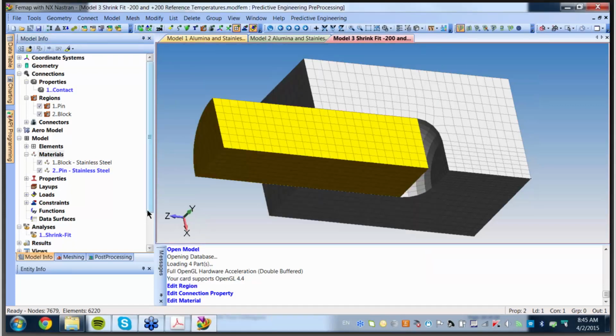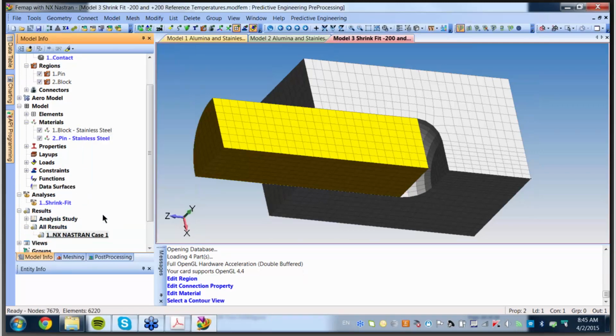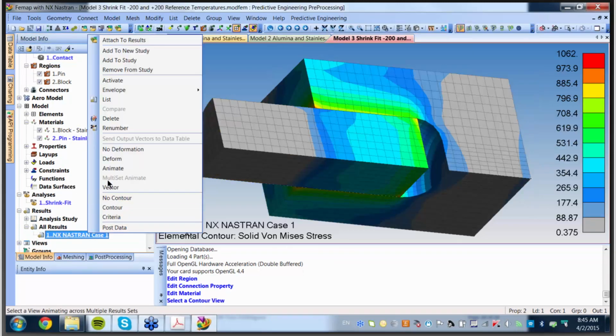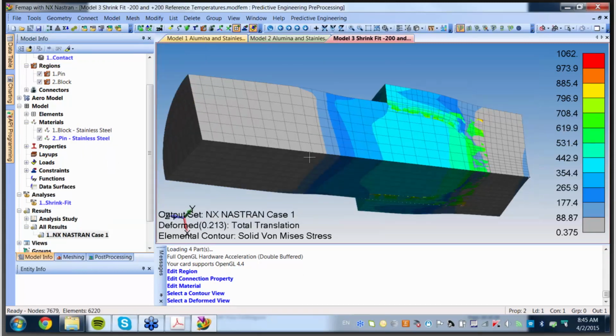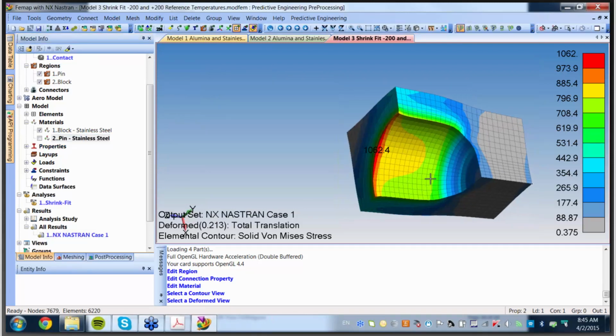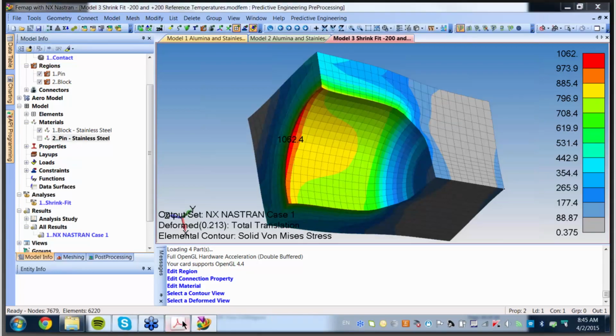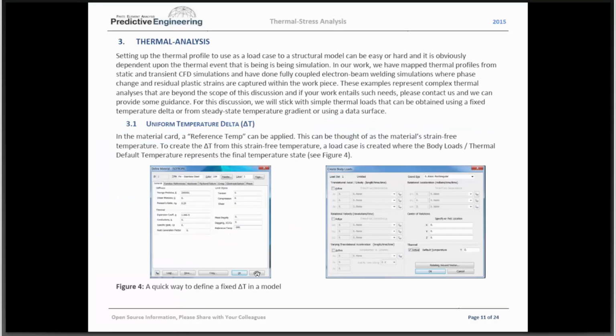And the results are down here. You can look at the deformed shape, and of course, that looks crazy, doesn't it? Because of the pin, so we'll just go in and blank it out. Then you get this beautiful looking picture for your quarter symmetry. Well, of course, because it's a demo model, it's going to look beautiful.